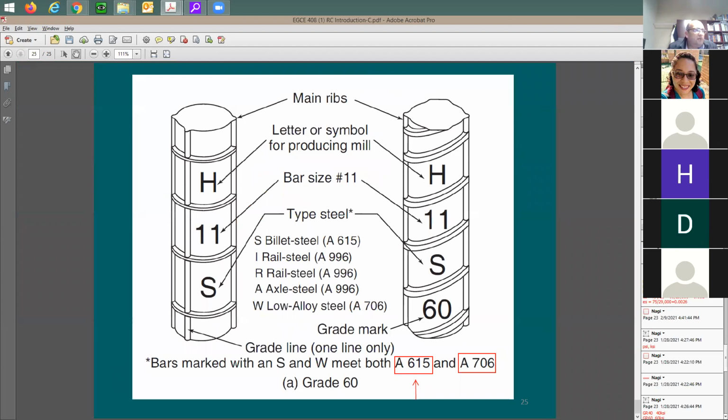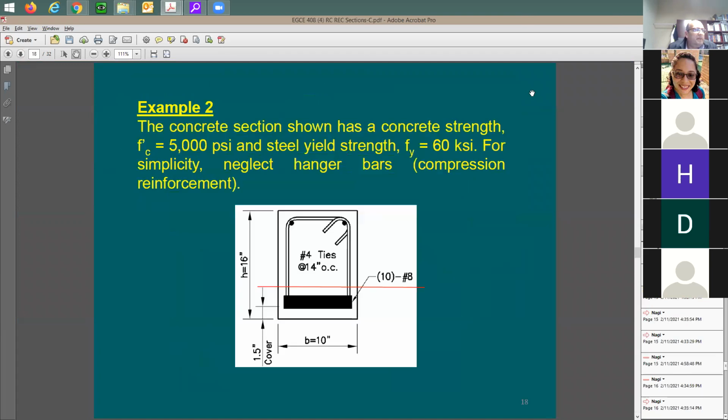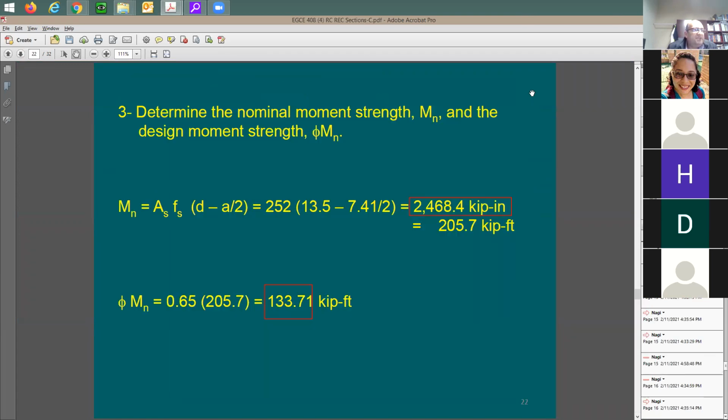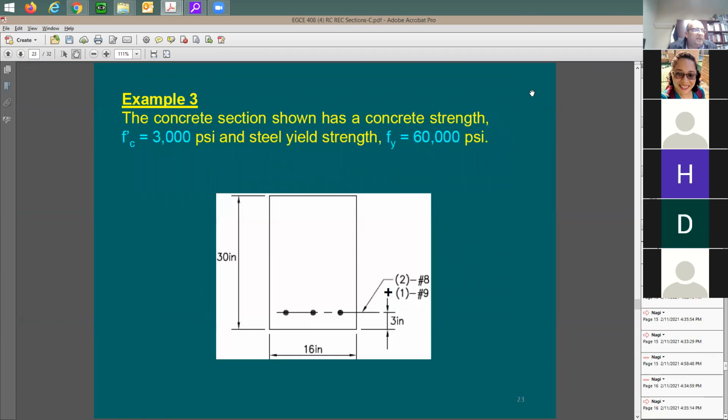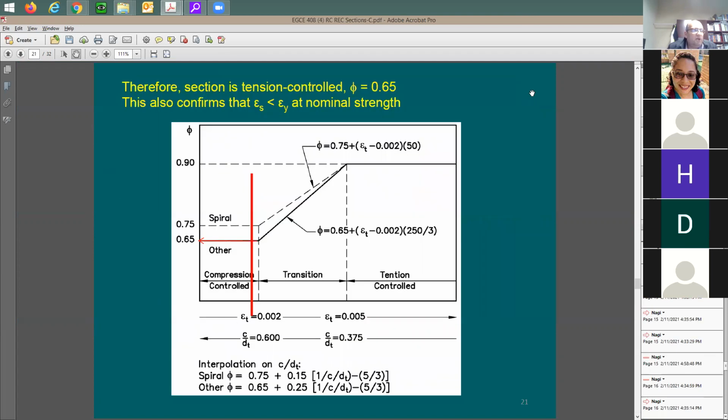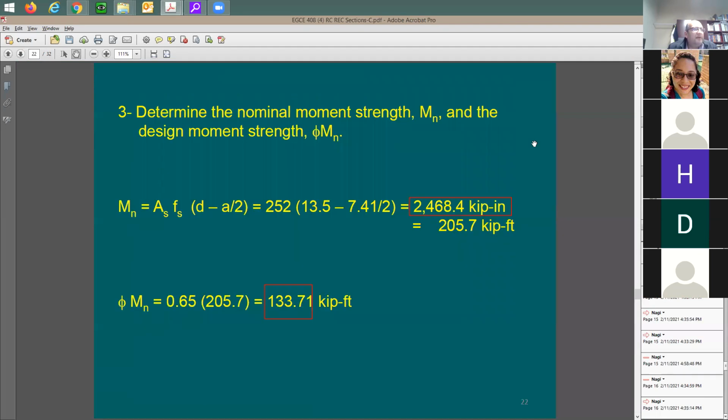Put this aside and go back here to our rectangular section analysis. So now we have seen the effect of adding lots of rebars and we understand what's going to happen. And we understand also we need to appreciate that when the steel is yielding, it's going to give you your ductile failure. It's going to be tension control failure and the whole thing.